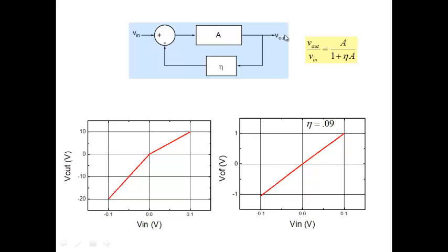A similar effect is happening in a bipolar transistor also. Same phenomenon is occurring. So when you put negative feedback, one of the benefits you get is linearization. Your characteristics, V out versus V in, get linearized and therefore the distortion reduces. The detailed mechanism of distortion reduction is that the input to the amplifier A itself becomes distorted. So this is what is happening inside our amplifier.